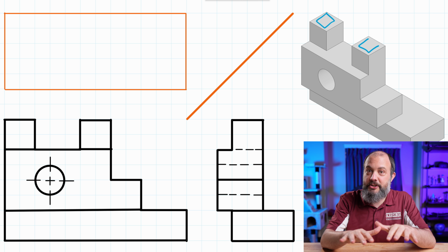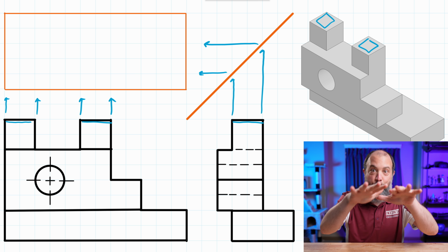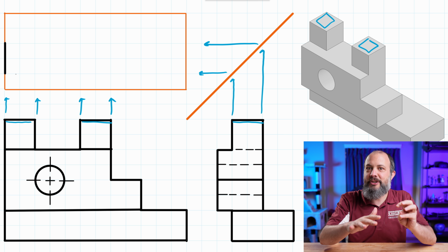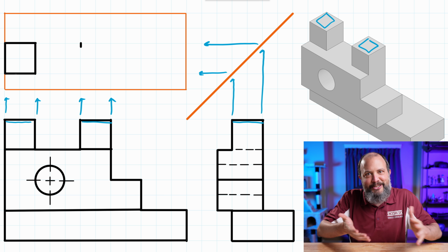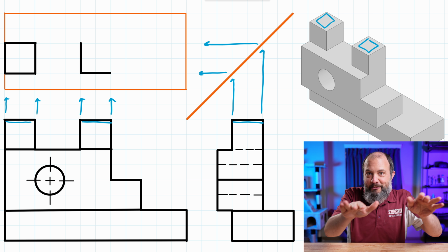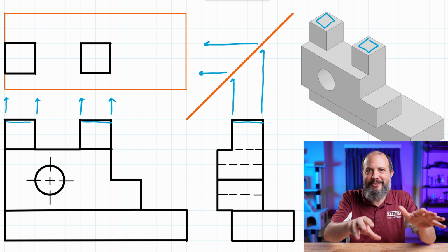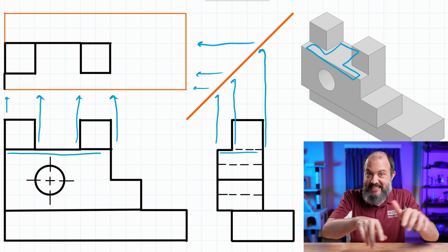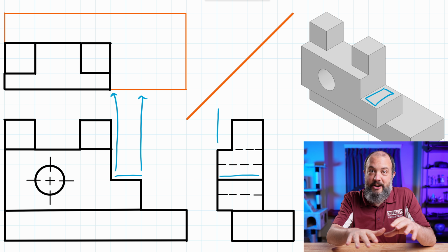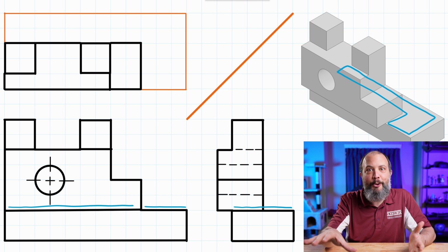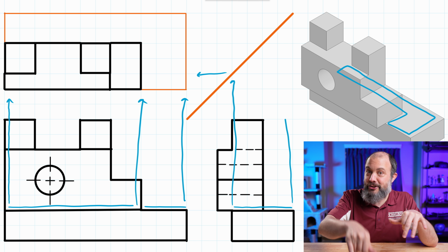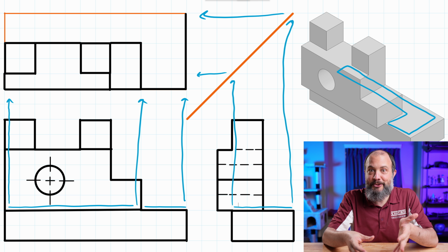On a top view, you're going to want to start at the top and work your way down, because that ensures that your visible lines will be visible, and then the things that are underneath other things you can draw as hidden. Tippity top first are these two rectangles. Next layer down will be that T shape. Another step down from there will be another visible rectangle. And then further over to the right-hand side, one more rectangle. Those are all of the visible surfaces looking from the top down at this 3D shape.